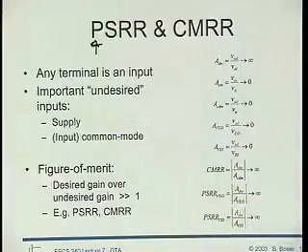But really, every circuit has lots of inputs. For example, every circuit has a power supply. Well, that's an input to the circuit, right? And the variations of the power supply, by now we know, are just a matter of life, or at least life for a circuit designer. Variations on the power supply shouldn't cause variations of the output of our circuit, or our amplifier in particular, right?